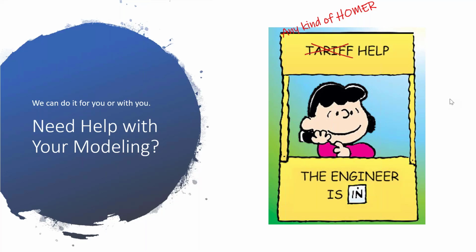Question about MultiYear and HOMER Grid, can you scale energy from demand separately? The way HOMER handles load growth is similar to the way we handle sensitivities on load. It's a multiplier that multiplies the entire profile. So let's say you said 10%, then in year 2, the load is 10% greater than year 1. That means the load in every time step, every hour, whatever your time steps are, is 10% higher than the previous year.